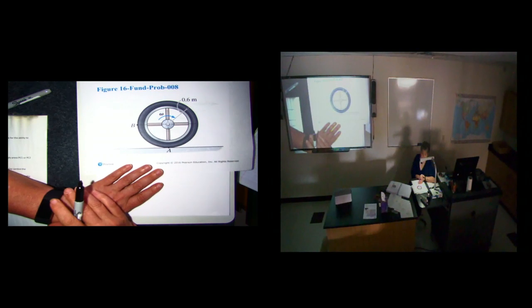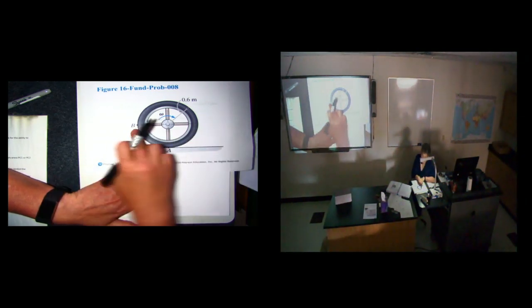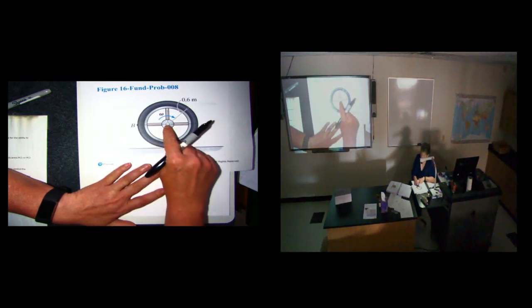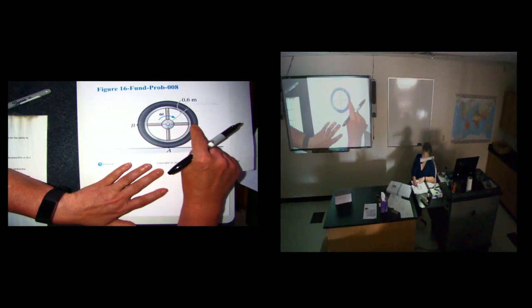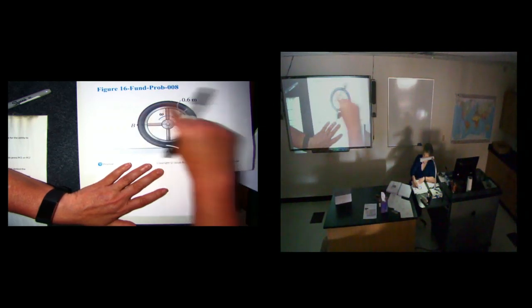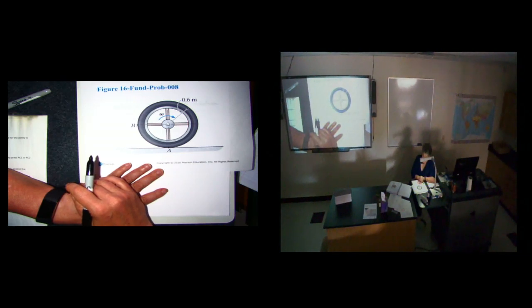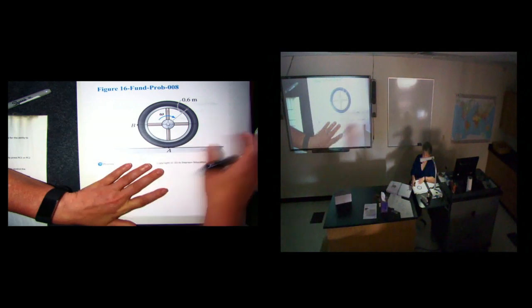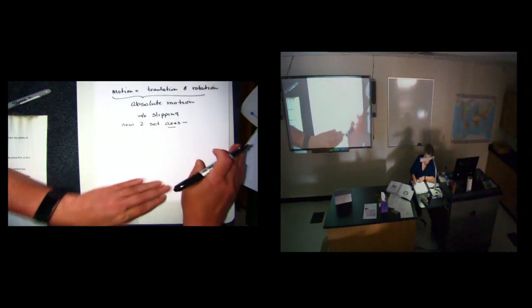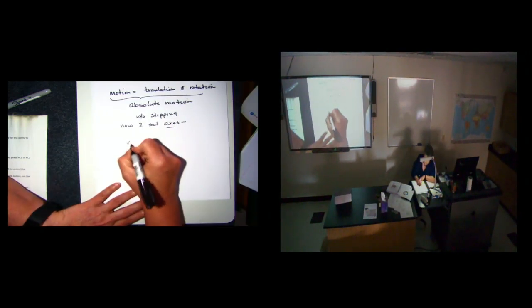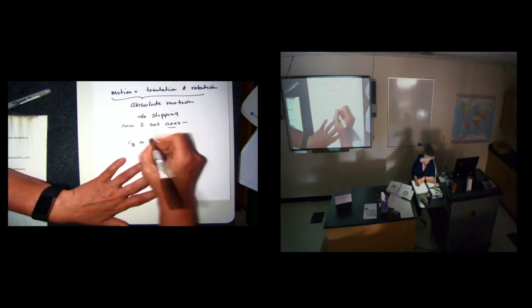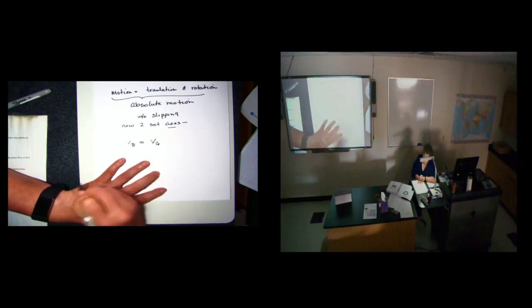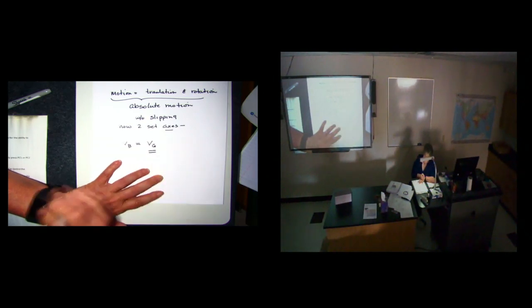And if I have my wheel here, we have a fixed radius. Radius is 0.6 meters. We're rotating around with an omega. We're going from A to B, and I can write that out in vector notation, and it's going to be minus 0.6 i, because I'm writing this relative vector from A to B. And we're given that omega, by the way, is 10 radians per second.